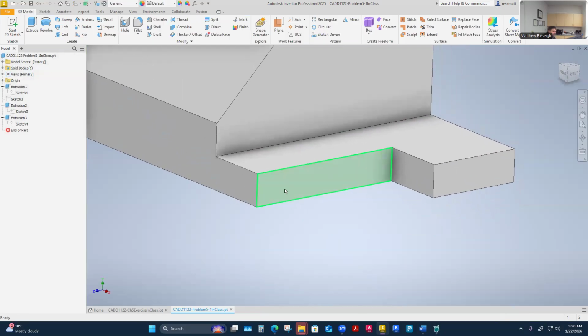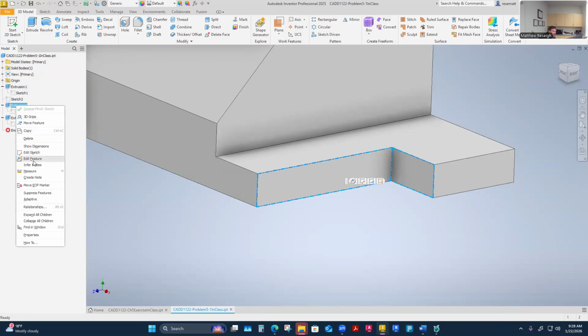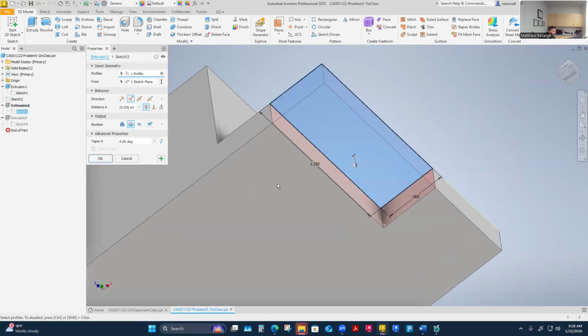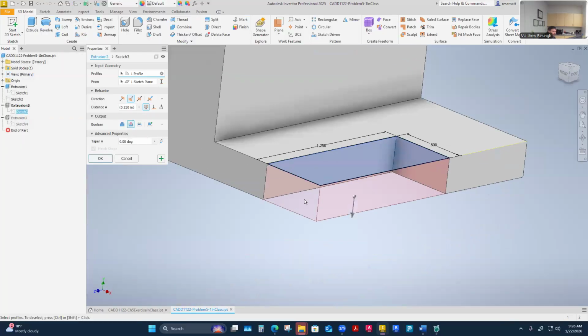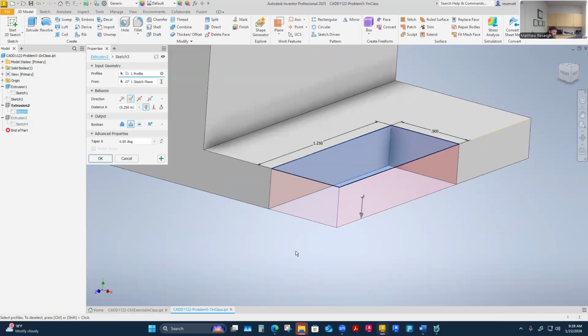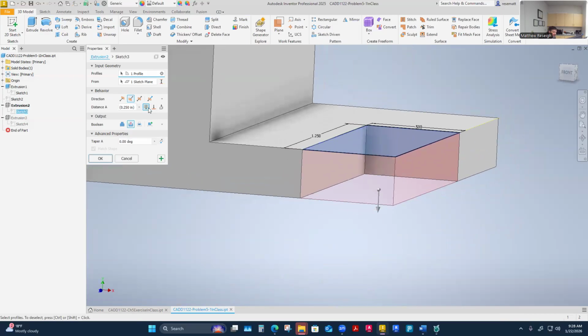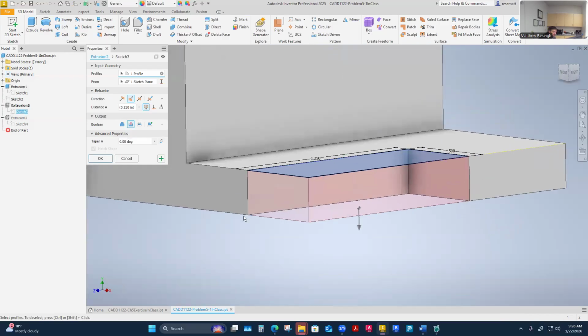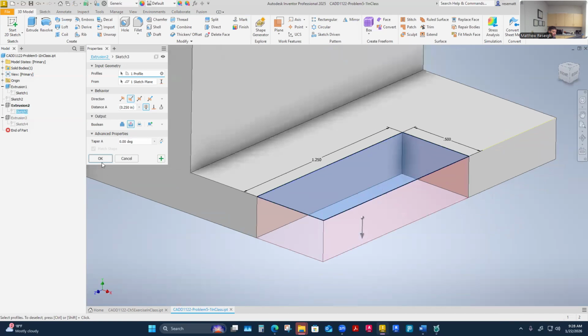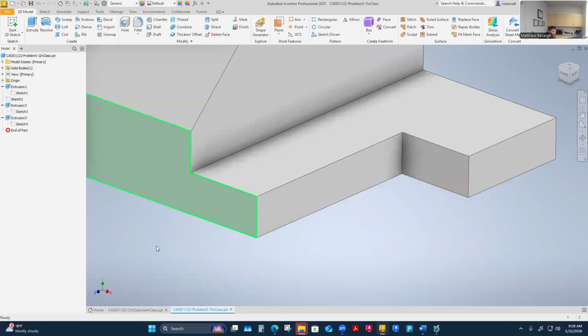we haven't changed the height of this. So if you ended up doing that extrusion, I'll go in and edit this feature now just to show you. Mine is a through to this back side, but if you had put in a 1/4 inch extrusion cut, it would still work fine because we haven't changed that dimension. Mine, I obviously had picked through to this side or through all. So no matter if I change this thickness, it's going to be cut through. So that one didn't need change for me.